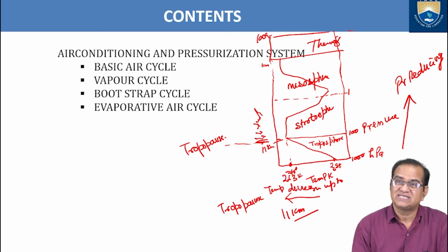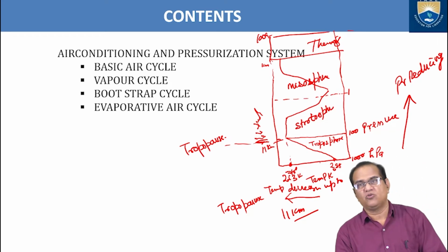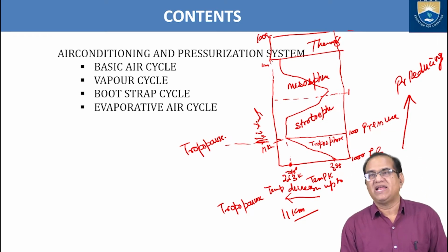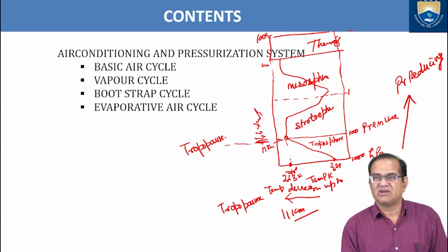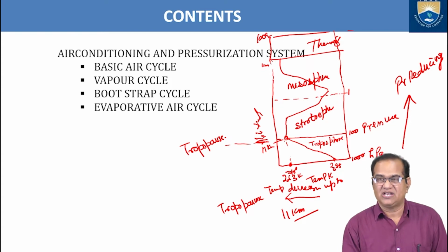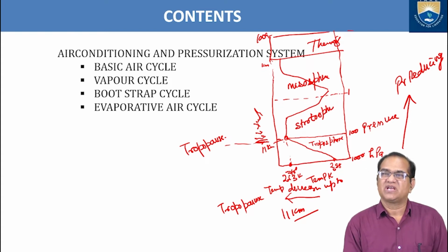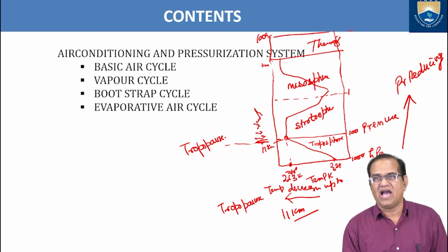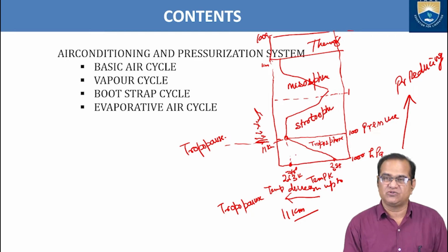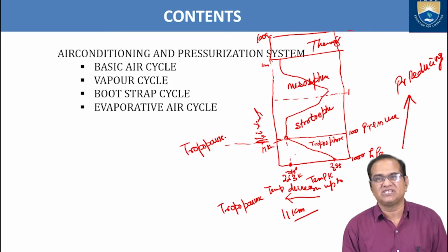But humans and equipment are not habituated to stay in this type of environment, and we need some knowledge of how our equipment, the human being and the pilot will survive this type of low pressure, low temperature and low density environment. Also, we should know that the lift is directly proportional to the density of the atmosphere. As you go higher and higher, the density of the atmosphere is reducing, and in the same way the lift of the aircraft and the thrust producing capacity of the engine is also reducing.